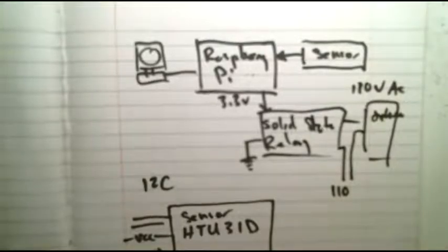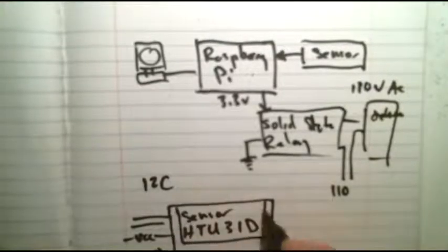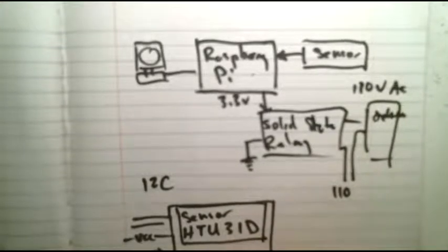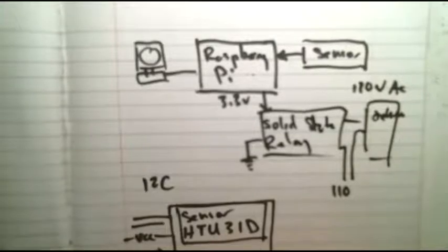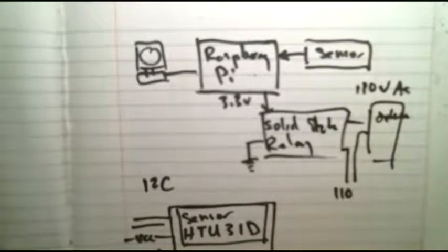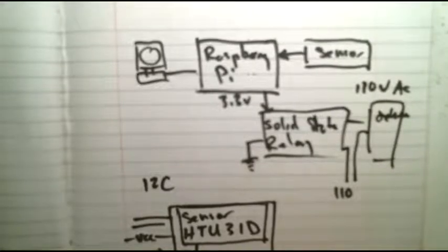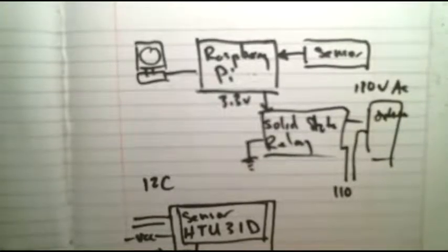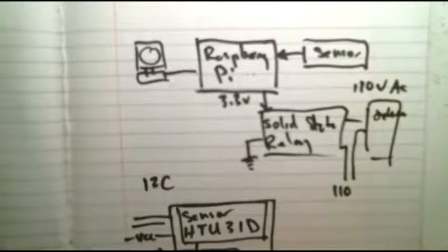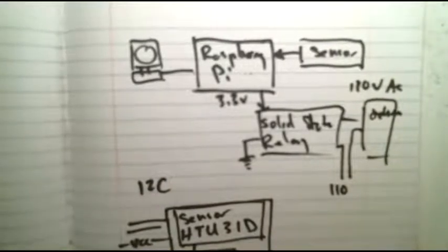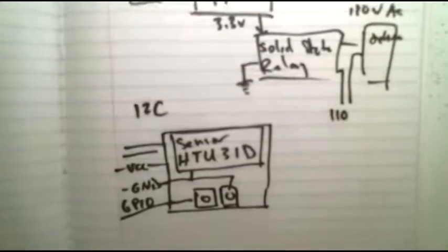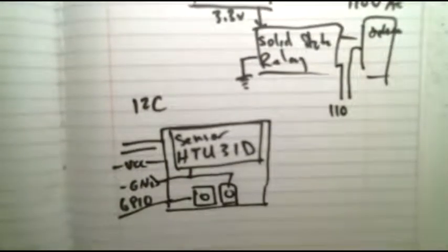And then on the same board, we're going to have the terminals the GPIOs connect to for the solid state relay. That'll just be a connection. We'll have another connection, one for the positive 3.3 and one for ground. All right, so that's what we're looking at, and now we'll talk a little bit about CadSoft EAGLE.